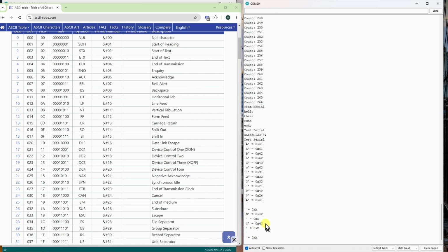And there they are. So there's our C. It sends the carriage return first. So that would move our head back to position 1. Then the line feed, so we advance to the next line. And that's what's happening up here when we do the print line. It's outputting one of these line feeds, maybe a carriage return as well, I'm not sure, but it's certainly outputting a line feed, and that's how the serial monitor knows to put a new line in.